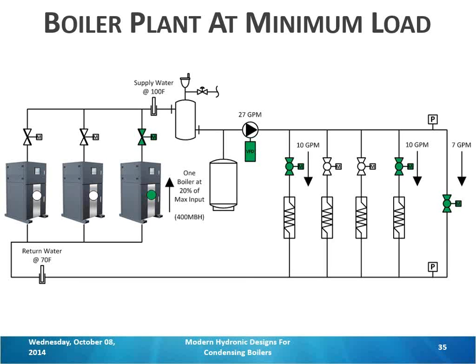There are other factors involved, like the type of burner and the turn down and that sort of thing. But general rule of thumb, if you're under 135, you begin to condense. So the colder you can get that water, the higher the efficiency.